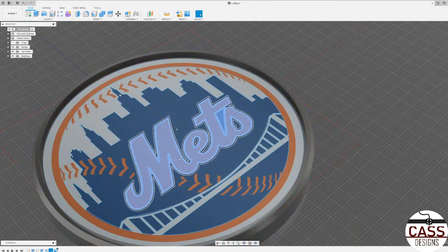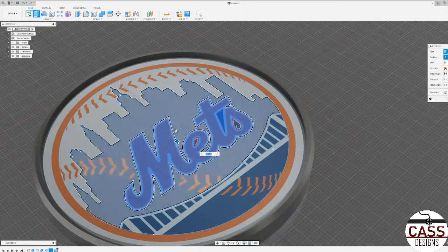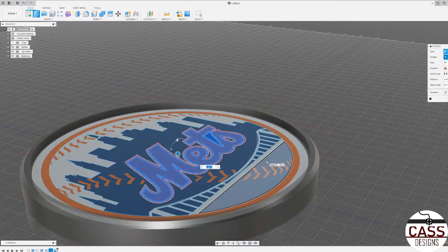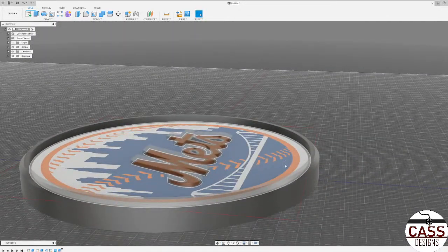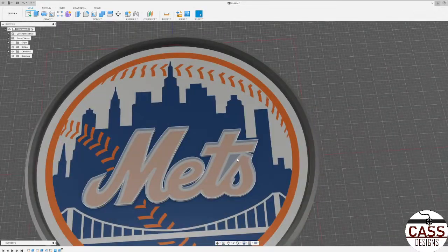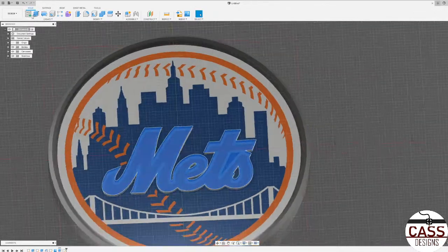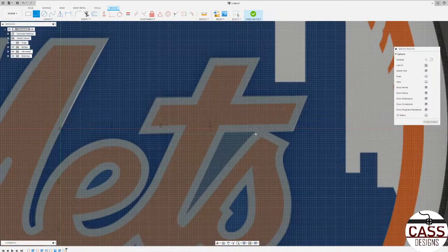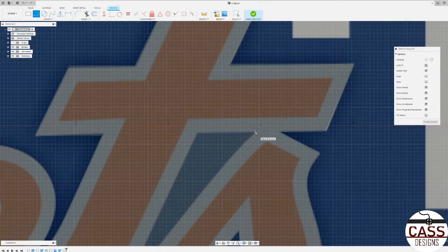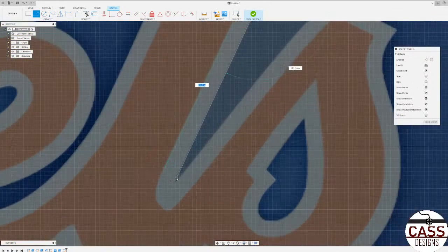What we'll do is we'll extrude this anyway. So I'm going to click E. I'm going to extrude this by about a 1/16 of an inch. So it's extruded, and then I'm going to create a new sketch on top of this surface to then cut from for this. And the reason I'm doing that is because for some reason when I open up that sketch, the image can't appear, so I want to make sure I get the right size cutout for this.